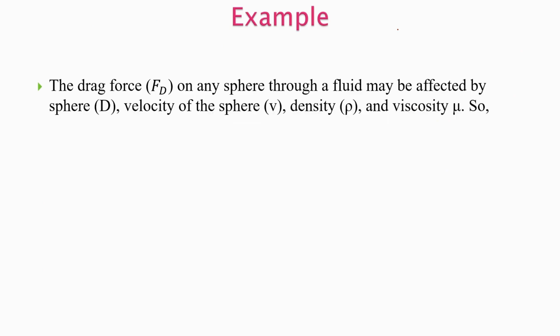So I have included an example: there is a sphere that is moving through any fluid. Let us say we have this pipe and fluid is moving in this pipe, and a 3D sphere is moving in this fluid in this direction. If anything moves in a fluid, a drag force acts on this sphere. So the drag force, Fd, is a function of the sphere through a fluid. This drag force is affected by sphere diameter d, velocity of the sphere v, density, and viscosity.